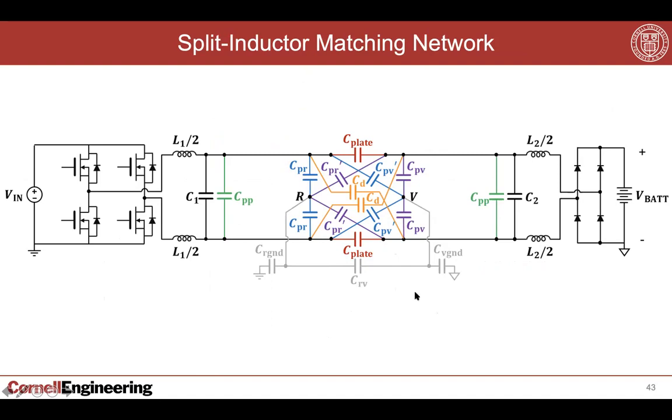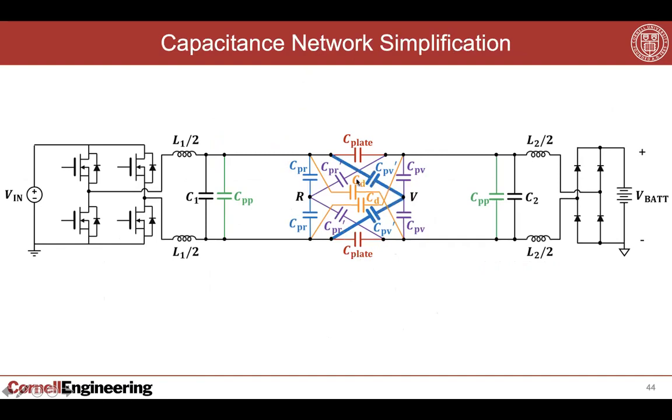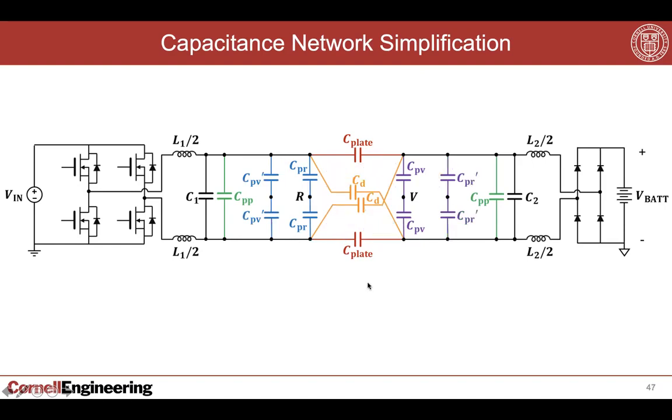First, observe that these two capacitances are actually carrying the same current because you have a current coming down from here. And this node is at the same potential relative to this as this potential is relative to that, because this voltage is positive something and this is the negative of that voltage. And so this is right in the middle. So the same current goes down here as was coming through here. Hence no current from here leaks out. So you can basically disconnect this node from here and just move it out. Similarly, you can play the same trick on these two capacitors and move that out.